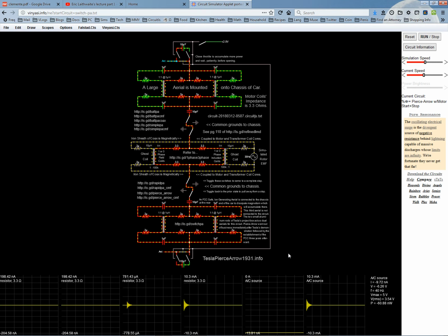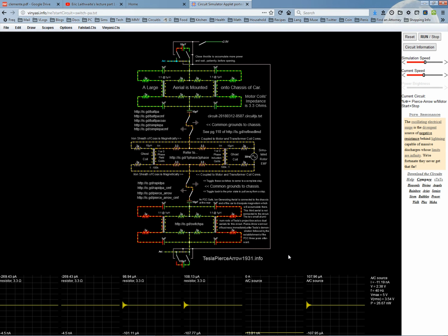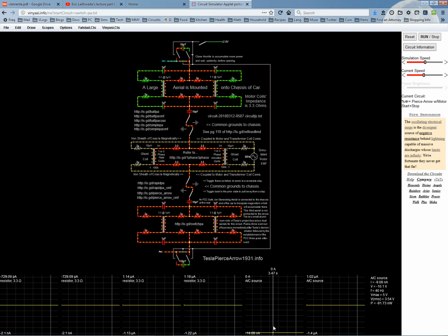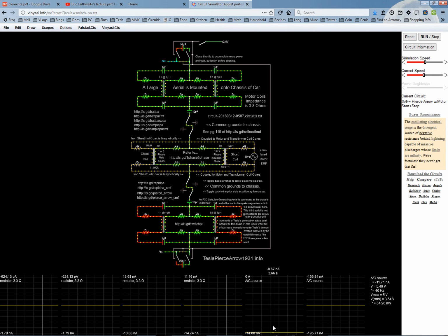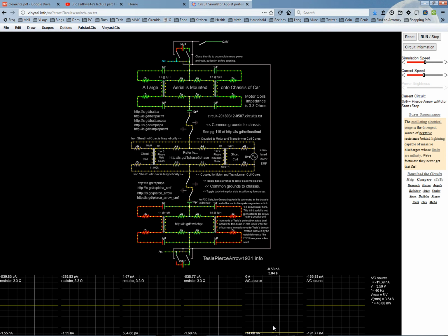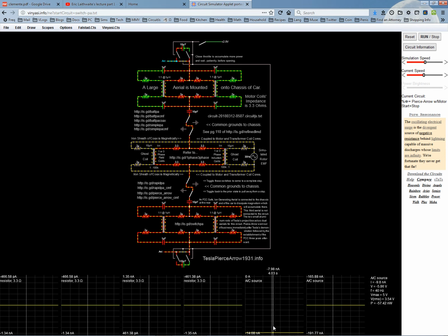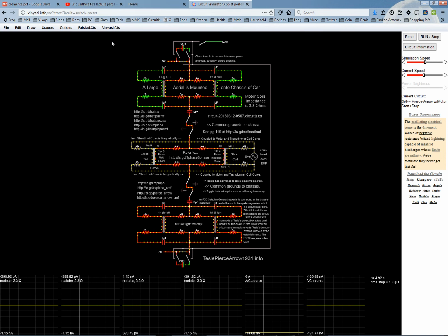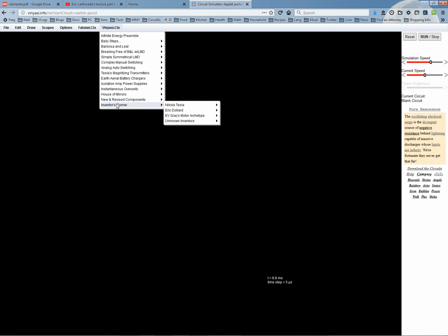So this one needs ionization of the aerial all the time, while the other one that we were just looking at, look at this, it's already down to nanoamps in the negative. So that's not a disturbance to the local environment. It doesn't take too long to reach that point, but before it does, there'll be a momentary surge that everybody will hear very loudly on their AM radio. It'll be like a kaboom of static, and then it'll quickly disappear, and people will complain. If you're the only one driving around, they'll locate you. They have means to triangulate and locate the disturbance and put a stop to it by raiding your place and taking everything, including your socks. So we don't want to get the FCC angry. That's the last thing we want to do.